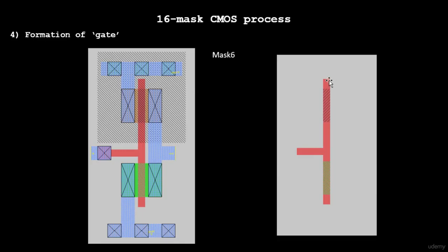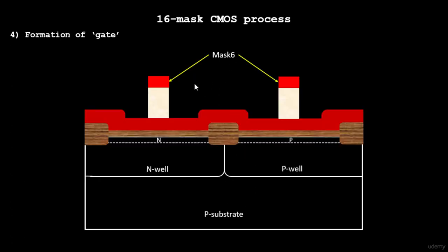But before jumping into the fabrication steps, let's look at a snippet from one of my courses called Circuit Design and Spice Simulation. In that course, we talked about the threshold voltage equation. The threshold voltage was very much dependent upon the body effect coefficient, gamma, and gamma is factored by the doping concentration Na and the oxide capacitance. So if you control the doping concentration and the oxide capacitance, that will impact your threshold